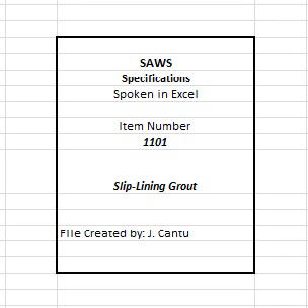4. Density/viscosity: the contractor shall design a grout mix with a density to prevent floating of the liner pipe. The apparent viscosity shall not exceed 20 seconds in accordance with ASTM C939-10, unless otherwise approved by the engineer.